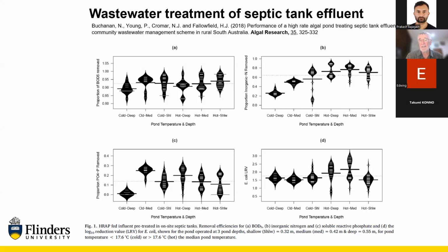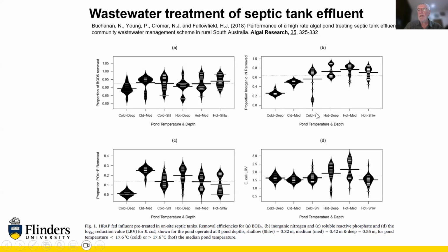Occasionally it goes up to 16,000, but generally it's 12,000 litres a day. You cannot ask people to stop using the toilet and to reduce the number of showers to change your retention time. One of the few controlling parameters you have is depth of operation. And that's been a question for a number of years. Is there any advantage? What we're asking here really is, is there any advantage in treatment performance terms to changing the depth at different times of the year?